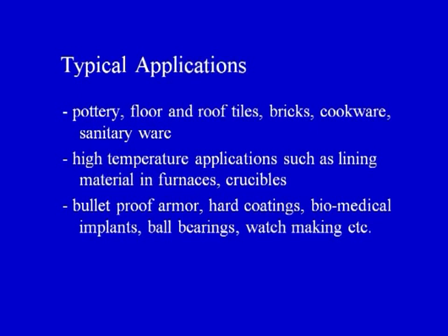We can have crucibles as high temperature or refractory applications of ceramics, and then we have high performance applications of ceramics, that is bulletproof armor, hard coatings on some metallic materials, biomedical implants, ball bearings, and as I have already discussed in today's lecture, in watch making the cases of the watch can be made scratch resistant with the help of ceramic materials.